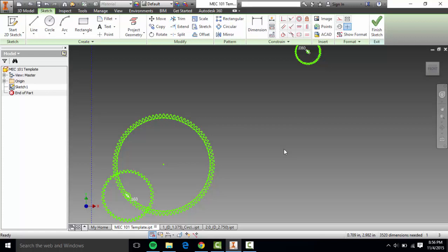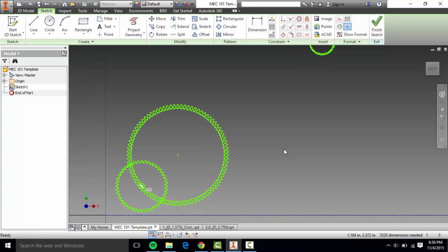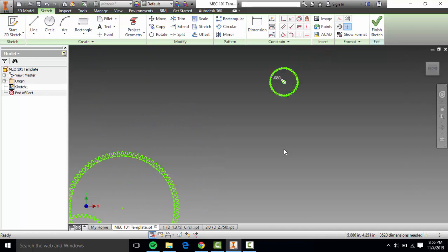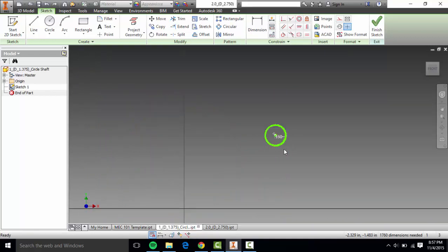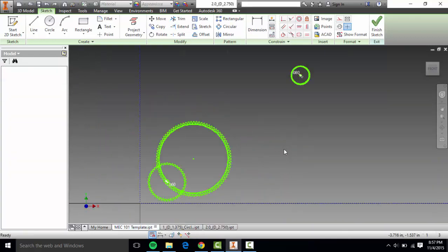So if you wanted these gears to mesh with this, you'd have to also scale them down to size. So if I wanted a gear that meshed with this, that had a gear ratio of 2, I couldn't use this gear that I've already brought in, because it has a different diametric pitch.